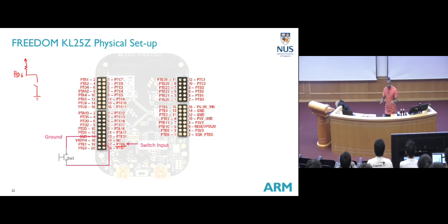Whoever is the best in your team, or if not, outsource to someone in another team. Whoever is good, ask them to help you, because you need to make sure all the soldering is correct, very neat and very nice. Don't over solder, don't overflow so that everything shorts each other and becomes chaotic. Be very careful, and also make sure when you solder, the chip is facing you. I have had people who solder the other way.